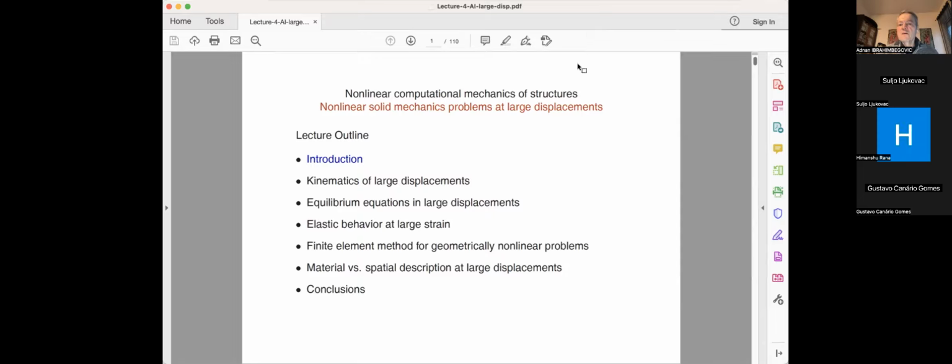Hence, especially in solid mechanics, where it is important which path you followed to get to a particular deformed configuration, because you have inelastic behavior, plasticity, damage, and so on, you often go back to the initial configuration, the one that you selected when you designed your system or structure, and you establish the equivalent form of the equilibrium equation in this initial configuration.